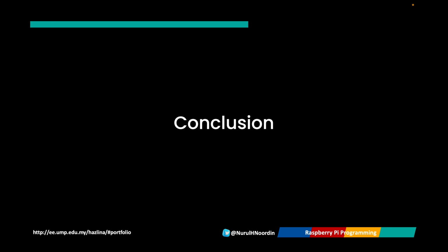Let's summarize what we have learned for this chapter. First, we looked into external libraries. External libraries make it easier to interact with hardware components. The SSD1306 library allows us to control OLED displays with Python. We learned to display text and graphics on the screen. Python libraries also help us connect with other external hardware like sensors.